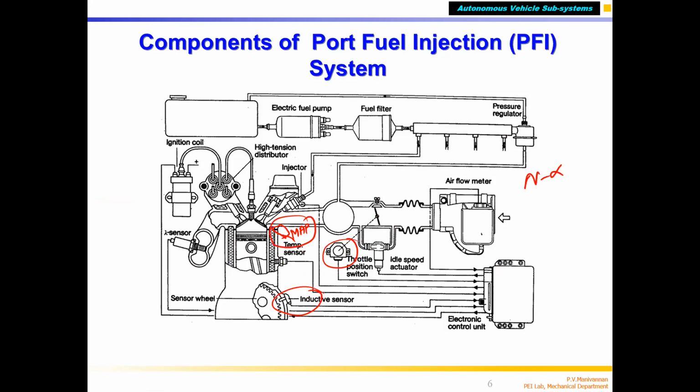Then you can add additional fuel quantity, because you know that when the vehicle load or engine load is increased, it sucks more air. How much air is sucked, you can calibrate using the MAP sensor. Again, you attach the MAP sensor, load the engine with different loads on a dynamometer, and you can measure the MAP sensor. Then you put a sensor which measures the amount of air mass that went inside in the lab, correct? Air mass sensor, correct? You measure that and you can add additional correction.